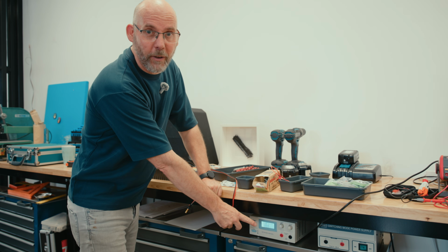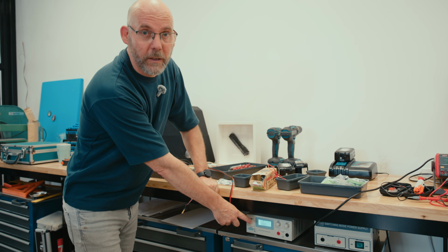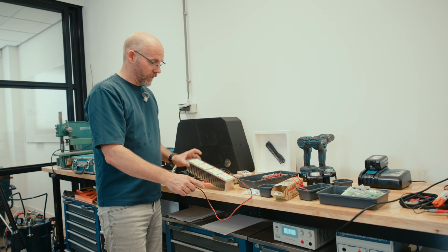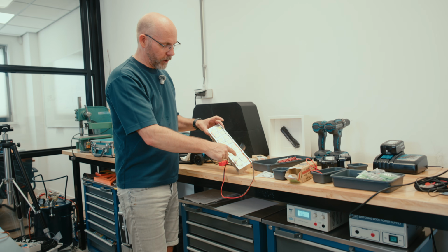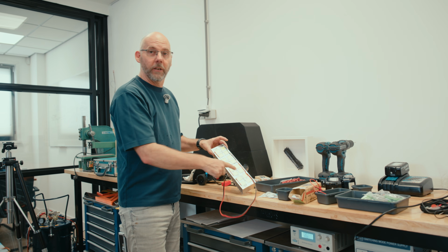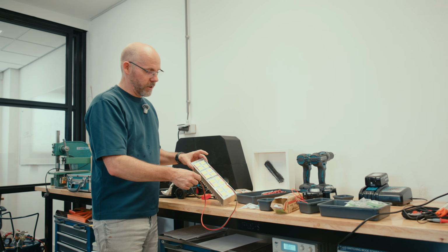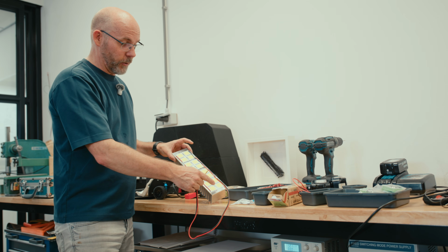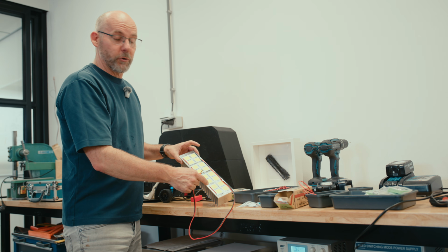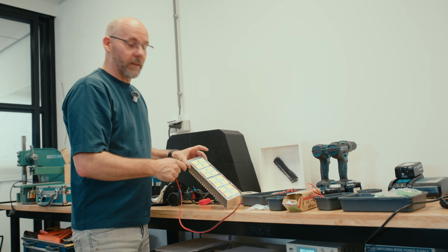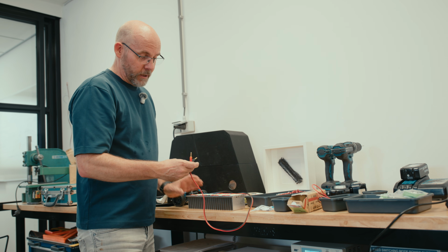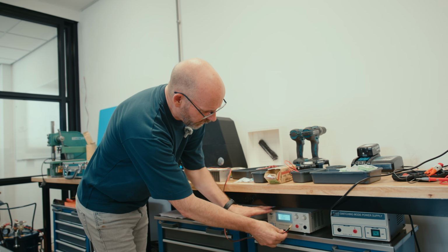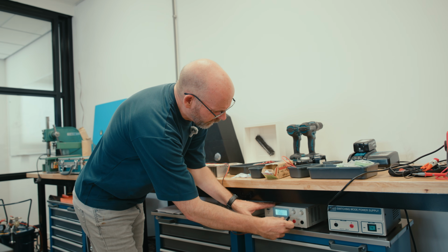I've got a power supply right here and it's set to 12 volts. These lights are actually 3 volts. So what I do is I've got 4 of them in parallel, and then 4 sets that are in series. Because I've got 4 of them in series, it's 4 times 3 is 12 volts, and 4 of them in a row. So it uses quite a bit of power, but nothing too crazy. So let's hook this up and let's see what it does.